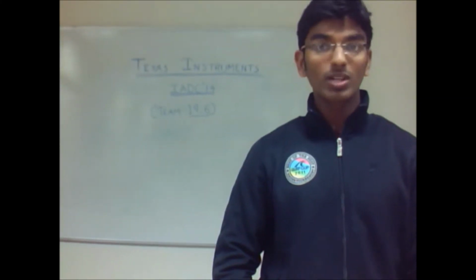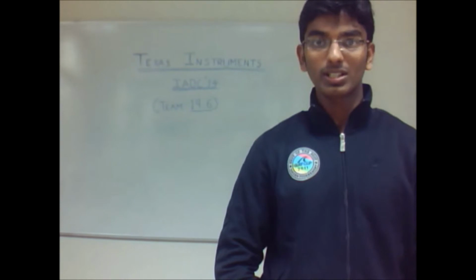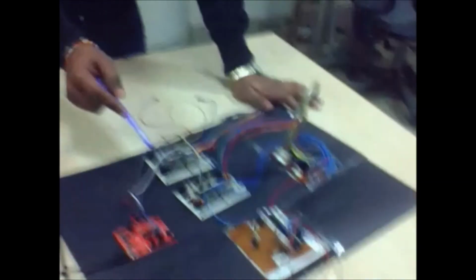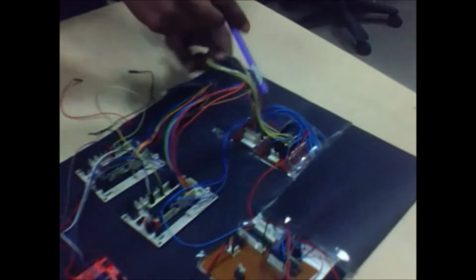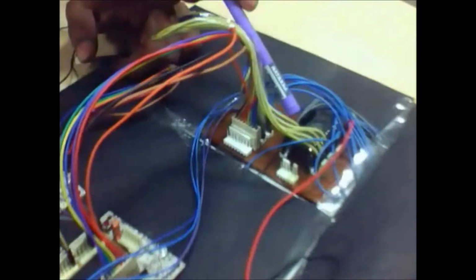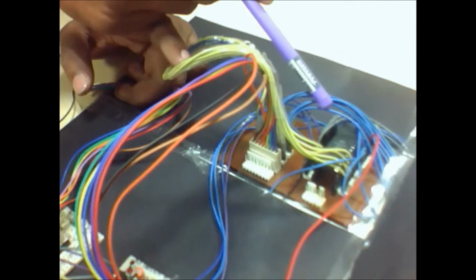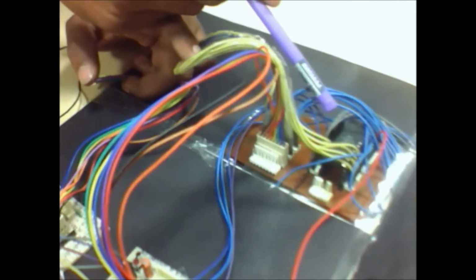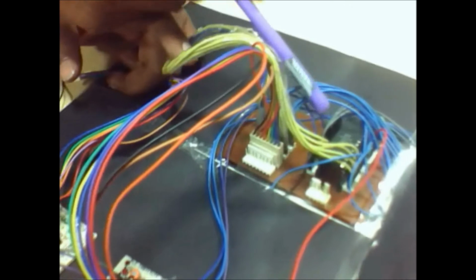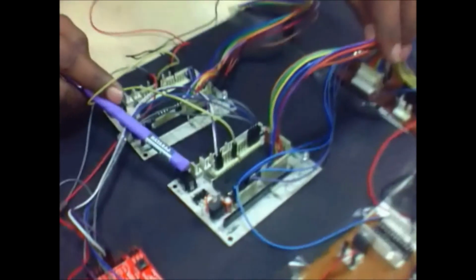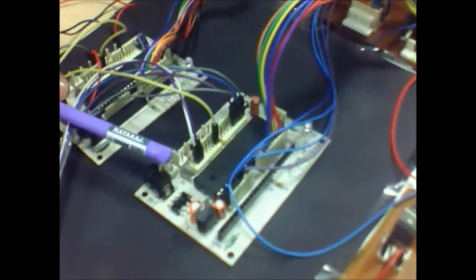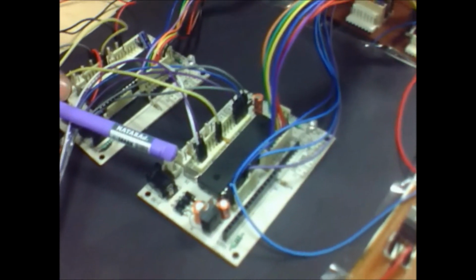Now we move on to the hardware implementation of our project. The hardware prototype has been shown here, in which various components are used. First, this is the EEPROM chip which holds the opcode for the program that is to be executed. This is an 8 kilobyte ROM, the 28C64A. The opcodes fetched from the EEPROM are taken by the microcontroller AT89S52, which executes the code.